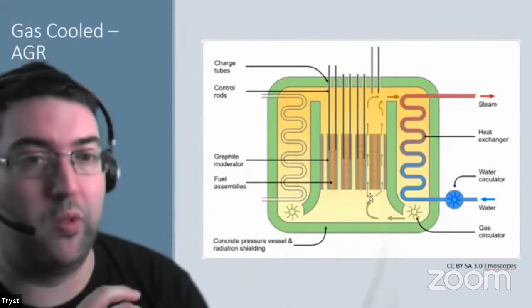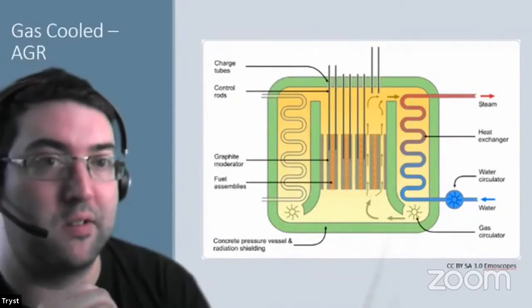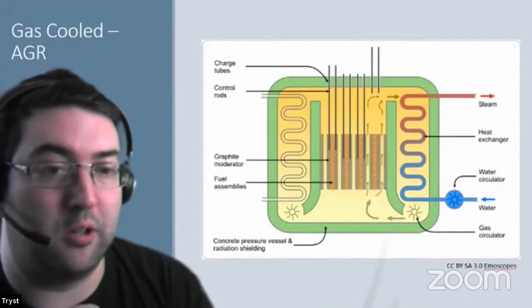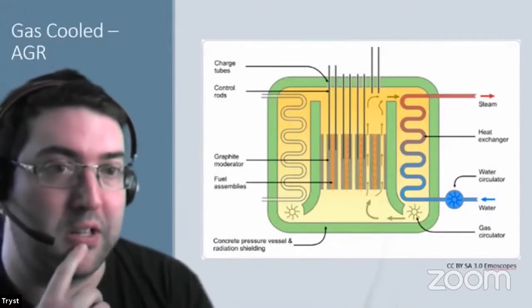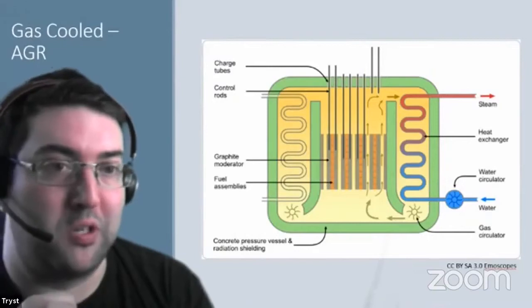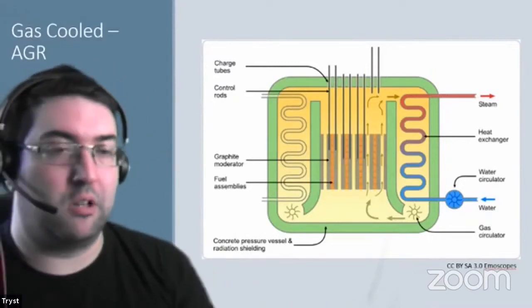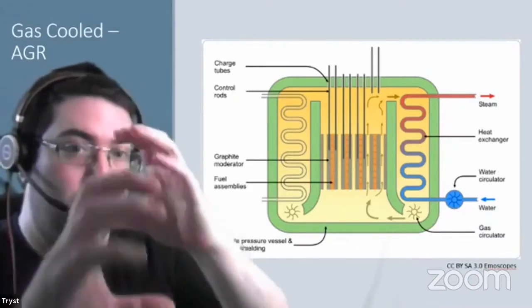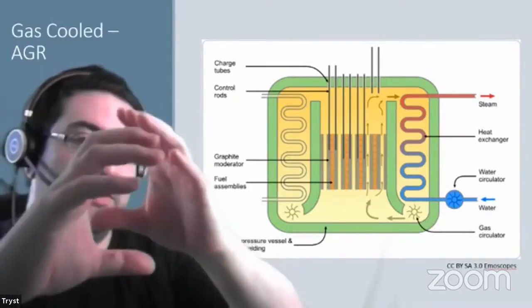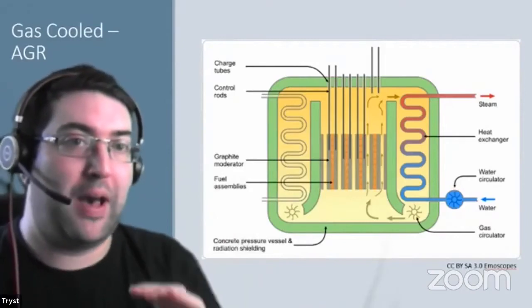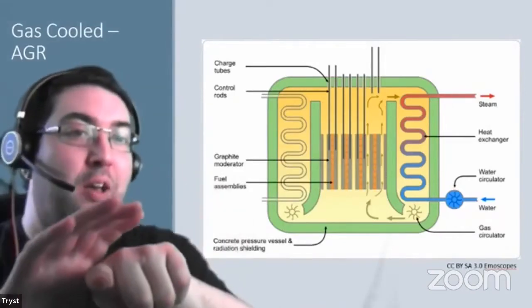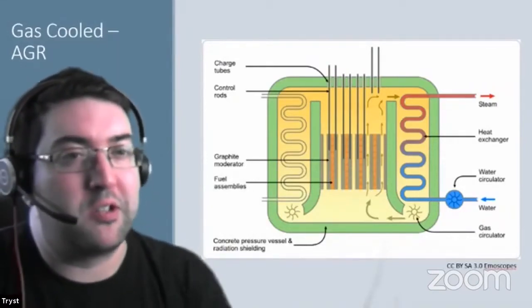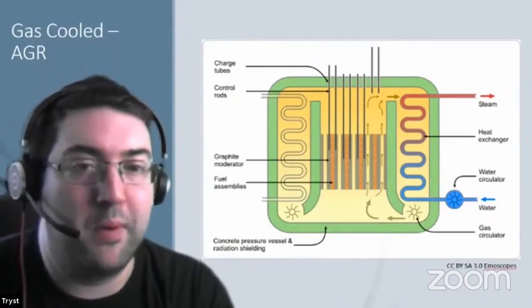So there's a big problem with the carbon cores inside these reactors cracking and breaking, and although that doesn't stop them from being good moderators, it does affect the mechanical properties of the core, so materials don't slide in and out as easily, because the hole that they go down is now all crooked, and that's bad, because if you needed to shove a control rod in there quickly, it might jam. So these reactors have a very limited life, which we've extended many, many times.